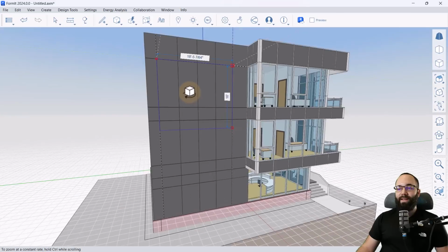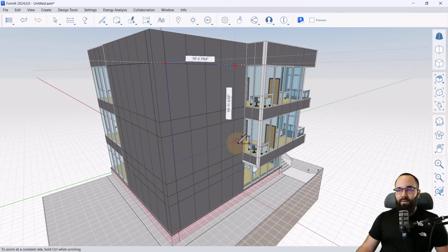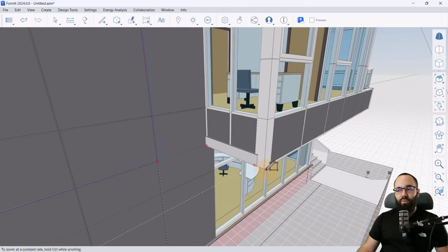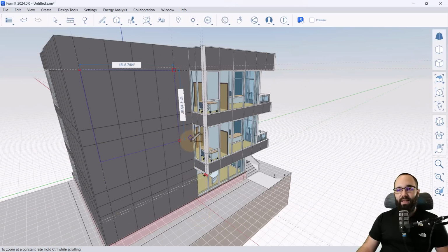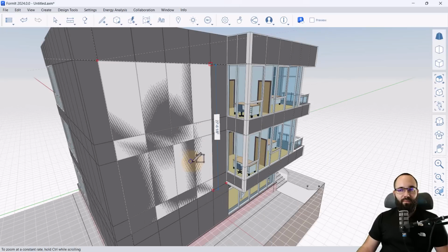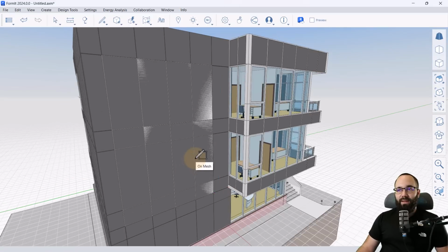And then we want to extend it down. Now see how it kind of figured out that we have the z-axis here. So what I can do is I can just hold the shift key, and now we can basically attach it to anything. So it's going to follow that z-axis, but it's going to figure out up to which point I want to go. So I can just click here, and as long as I'm holding the shift key, see how it's locked down. When I release the shift key, it's going to go off to the side like this, but first we can define it to go down the z-axis, hold the shift key, and now I can just click here in this corner, and it's going to place that rectangle there. Hit the escape key a couple of times.